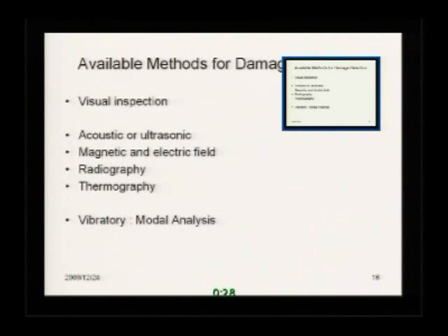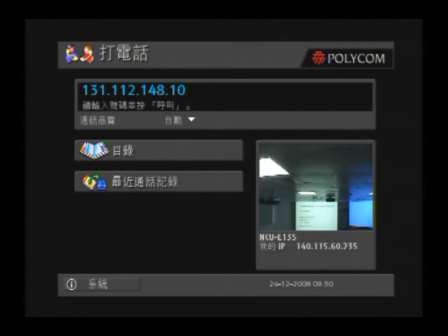Why? Because most of the bridges that we've seen are concrete bridges, and concrete is a very inhomogeneous material. When you build a bridge, you just specify that you need a very strong, very good concrete, for example 3,000 psi or 4,000 psi concrete. When the concrete mixer comes, you can check the concrete. If it satisfies your specification, you have to use it.